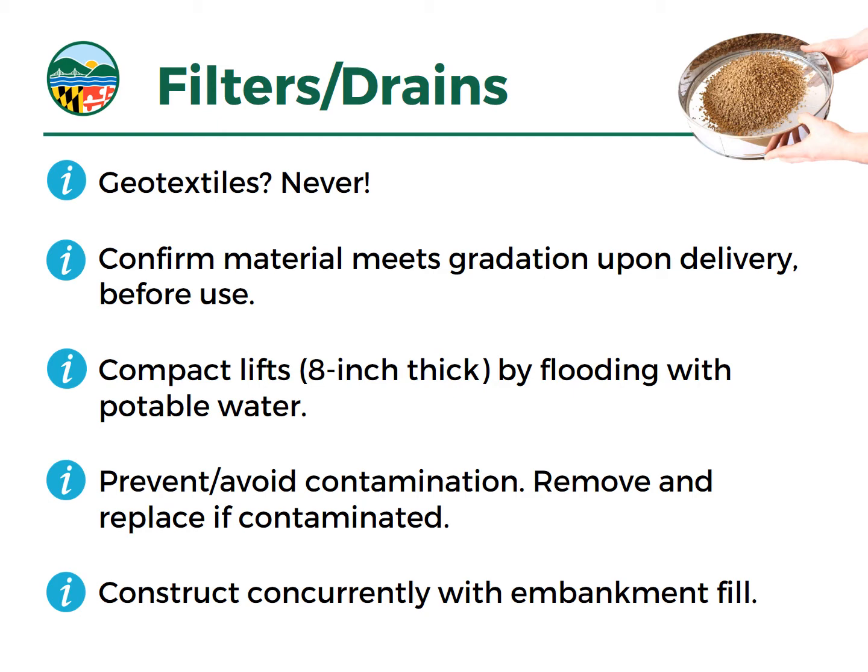So the aggregate supplier had to pick it back up and haul it off the site and deliver new stuff. That was a good call and a good catch, because particularly in filters and drains, the presence of fines can really adversely impact their effectiveness. So we don't want that in there.